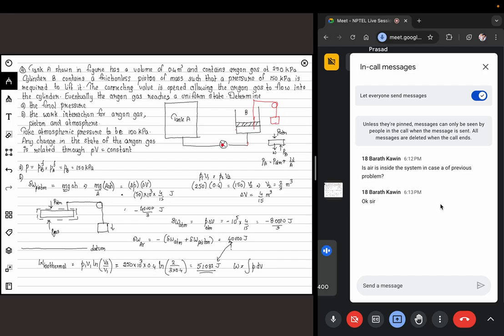There is a pressure difference across the valve, but I cannot use that pressure difference to generate any displacement work that I can calculate. So this difference between the 40,000 and 51,000 is essentially wasted in order to ensure that you have a reversible process or a fully resisted process.